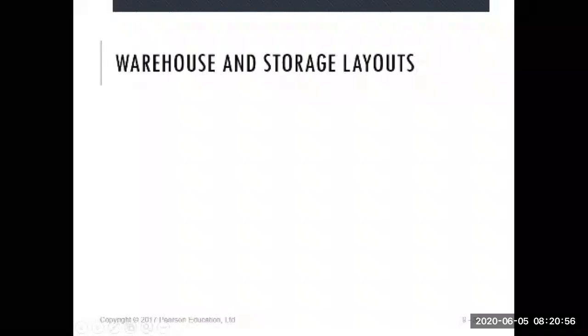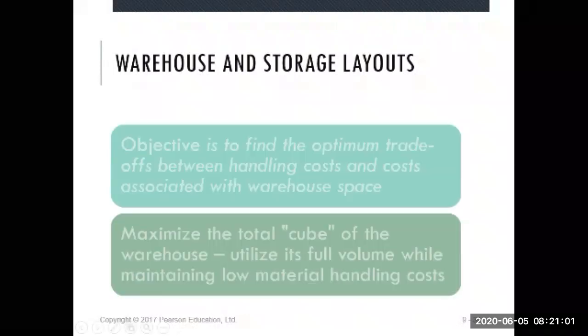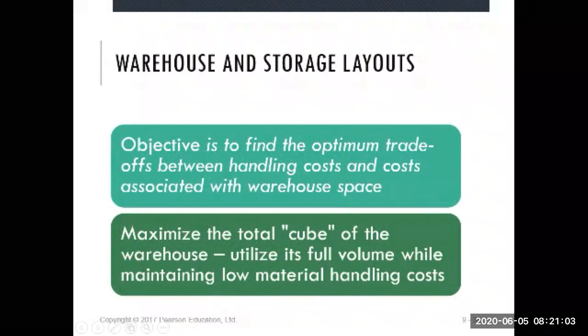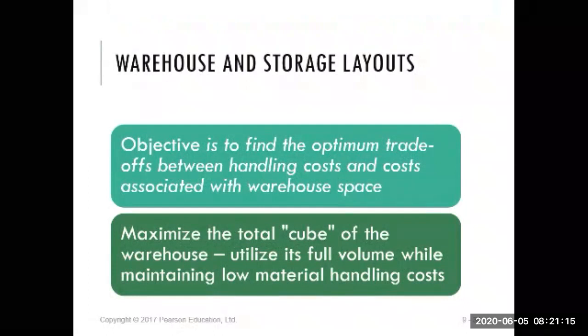Okay, so the third layout, the next one is the warehouse or the storage layout. The objective for this type of layout, different layouts have different objectives. The objective of this layout is to find the optimum trade-off between the handling cost and the cost associated with warehouse space, because remember, warehouses have to handle a lot of stock and different types of products.